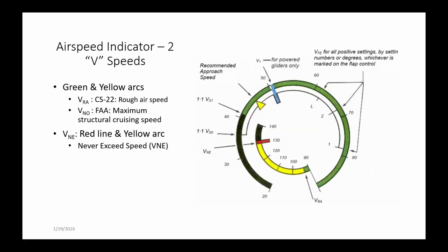So the key about the maneuvering speed is that you shouldn't be able to damage the aircraft with full control deflection. The VRA, the turbulent penetration speed, also can depend on the mass of the aircraft. So as you're lighter than, below your max takeoff weight, that actually could come down a little bit, but nowhere do I find something that says how you're supposed to derate.